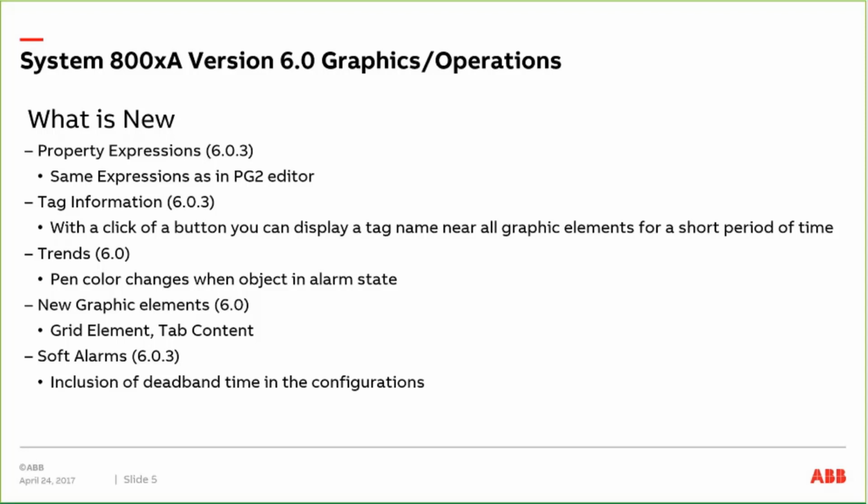Some new graphic elements that are also part of System 800XA version 6 are a grid element and tab content. New to 6.03 for soft alarms, because this has been requested quite a lot, is the inclusion of deadband time in the configuration. So now we can say we don't want that soft alarm to go into alarm unless it's been in a state for more than, say, 3 seconds.